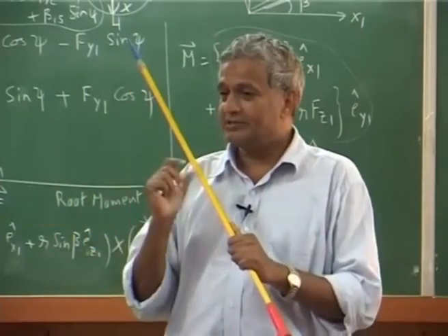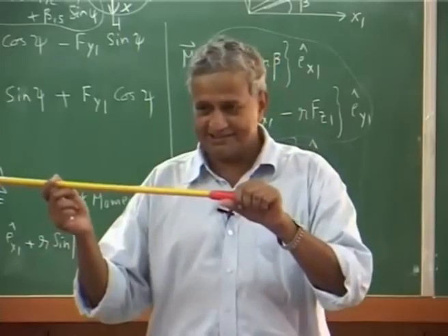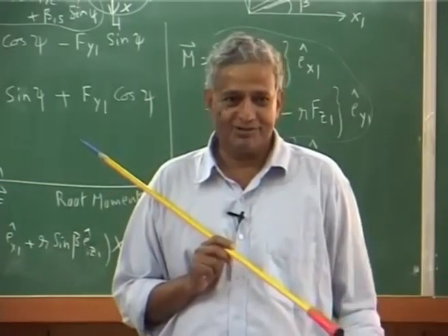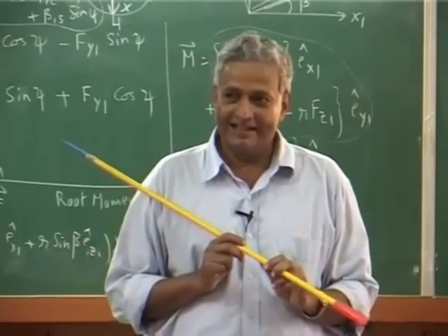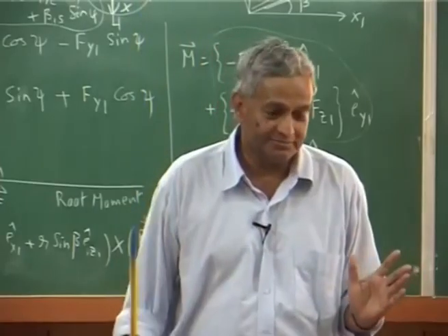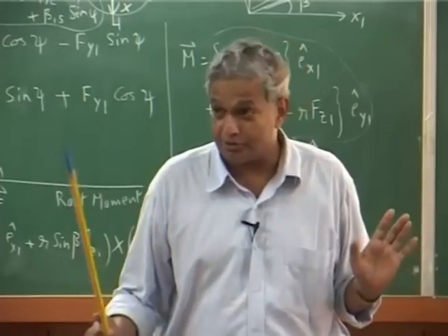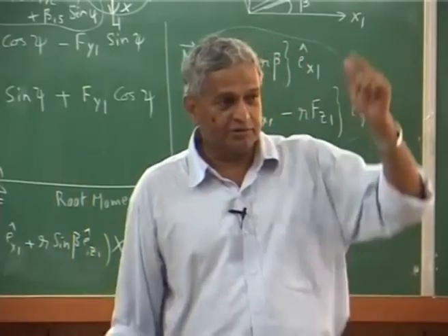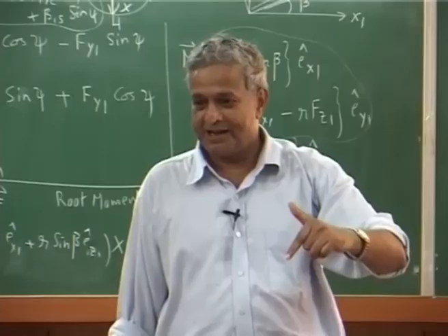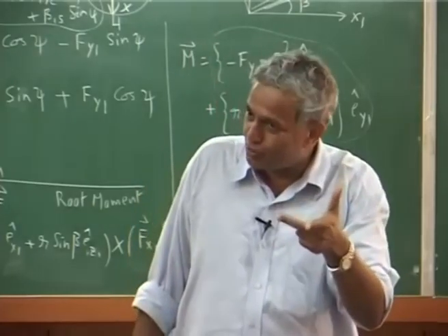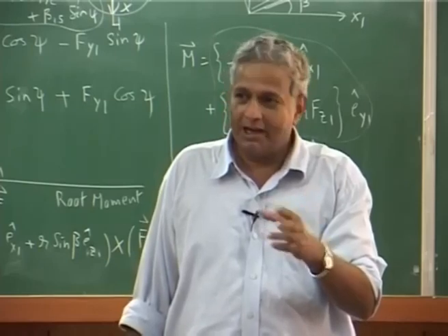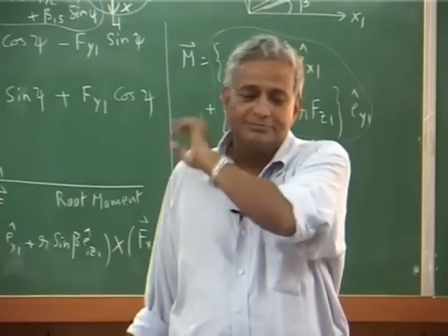The tail rotor not only gives a torque, it also gives a side force, so the side force has to be balanced. Now, what is the attitude of the helicopter? Please understand, because these are all hub loads, you have to transfer the hub load to the CG, and you have the CG coordinate system, and transfer the tail load to the CG.